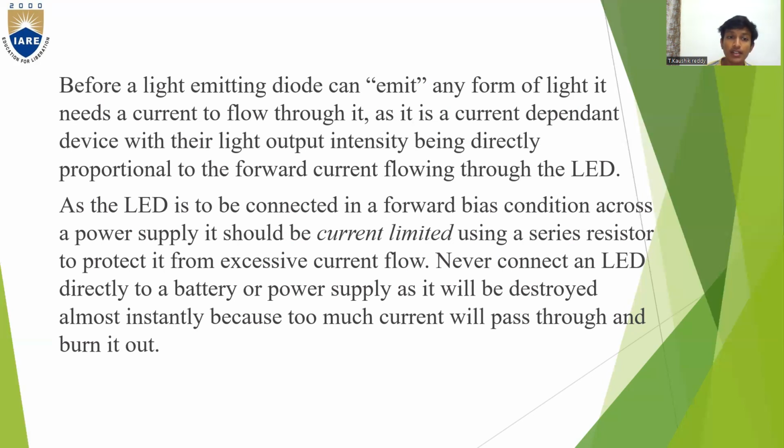Never connect an LED directly to a battery or power supply, as it will be destroyed almost instantly, because too much current will be passed through it and burn it out. So basically, you shouldn't directly connect an LED to the power supply or the battery, because a lot of current is produced, so it may blast or burn out. So be careful. Don't connect an LED directly to a power supply or the battery.